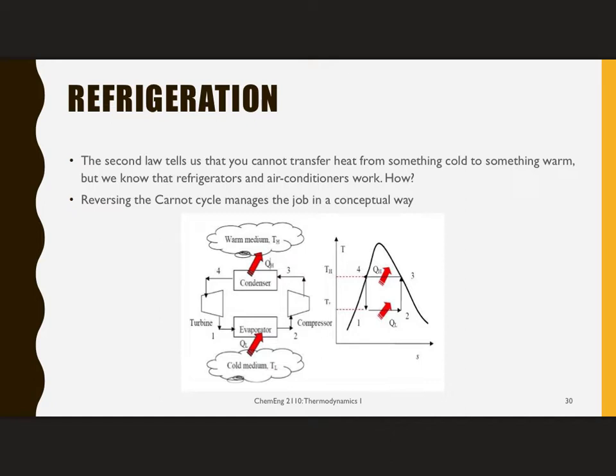The Carnot cycle doesn't work, right? It's an imaginary ideal cycle. But if you reverse it, it becomes a refrigerator. And so we can go through all of the steps exactly for this ideal cycle as a refrigerator going one direction, a heat engine going the other direction. But this is simply going to give us the optimal, what could be done.